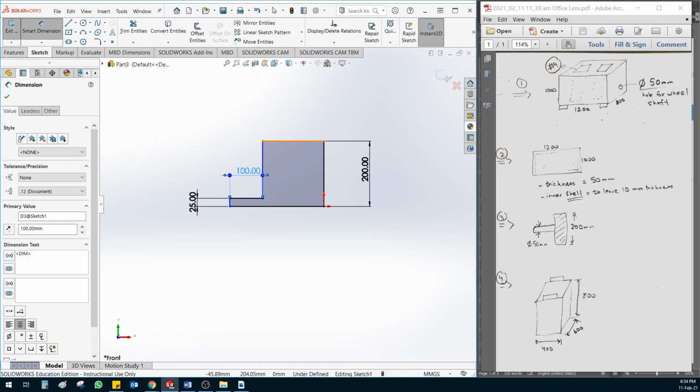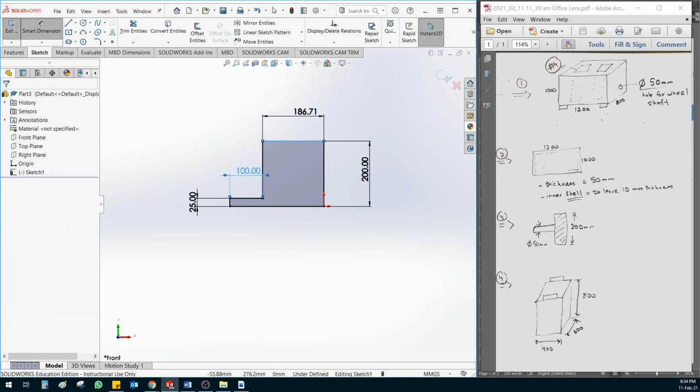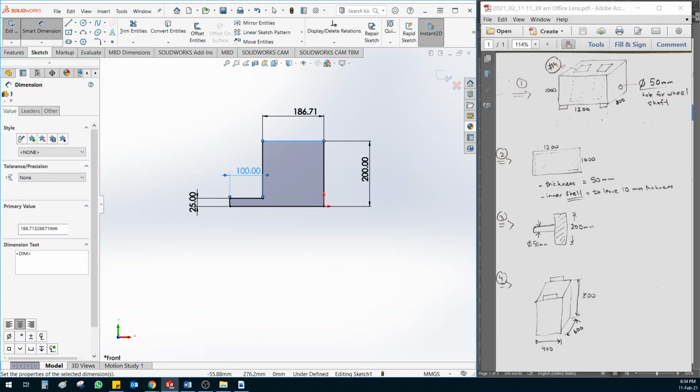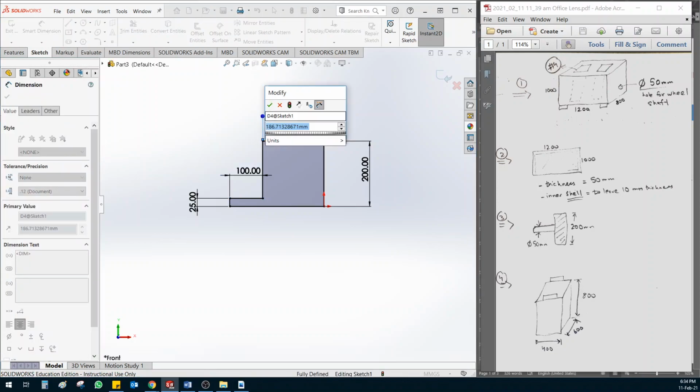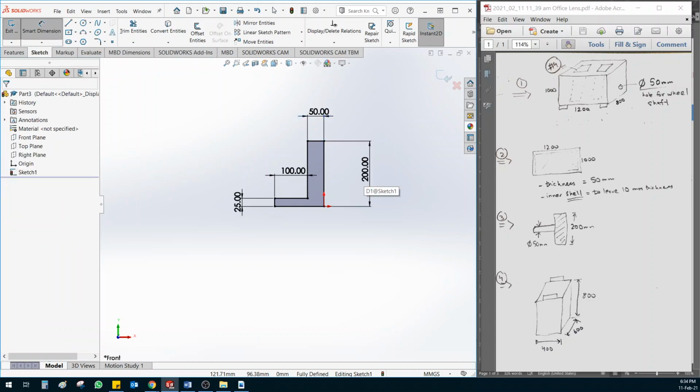So let's give this also the thickness of the wheel. In this case, let's give the thickness of the wheel to be 50. This is a reasonable thickness for the wheel. And this is just something you can play around with as you think it's looking good. Yes, I have made a mistake. This should be half of 200, so it should be 100 here.